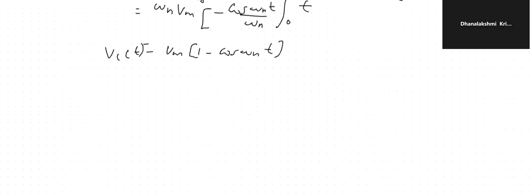Finally we get Vc of t is equal to Vm, substituting the limits t and 0, 1 minus cos omega n t. This expression is called the restriking voltage.